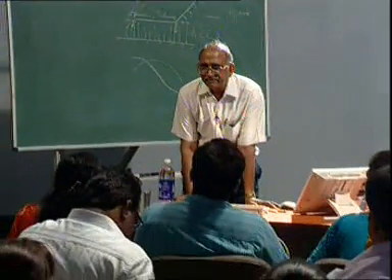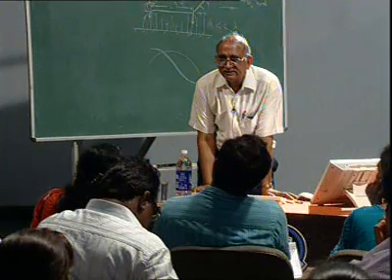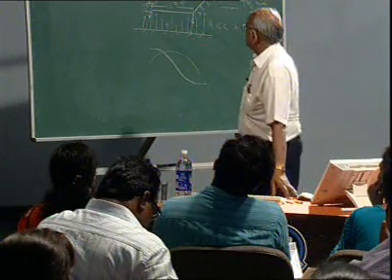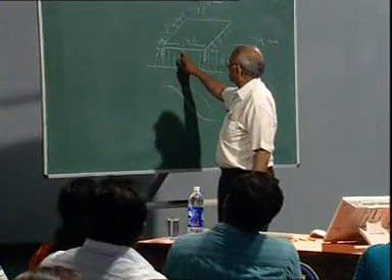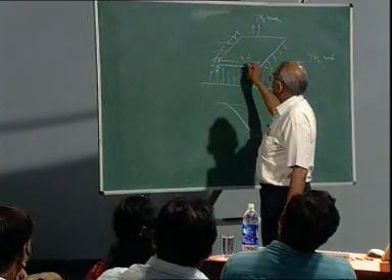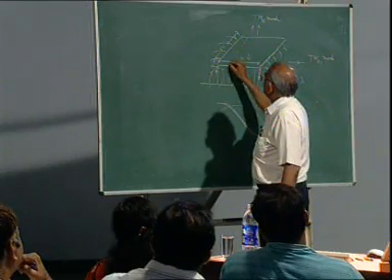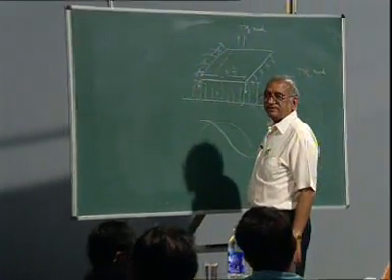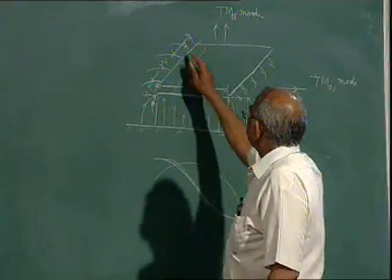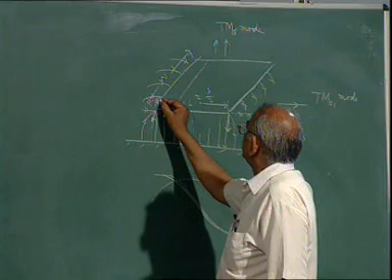Naturally, the feed point will be different. If I feed the patch antenna from the length side. Which side? This one? Yes. Yeah. If you are feeding it from this side, see what we have seen, that if you want to excite this mode, you have to feed somewhere here on this line. Okay. But if you want to excite the mode along this one, just wait.